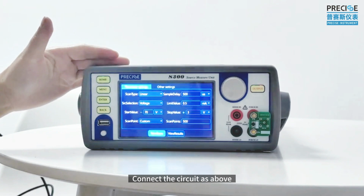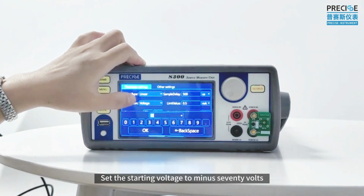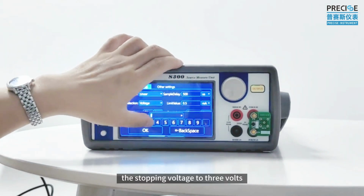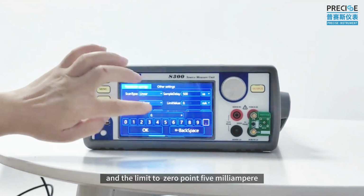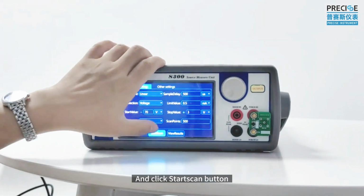Connect the circuit as above. Set the starting voltage to -70 volts, the stopping voltage to 3 volts, and the limit to 0.5 milliamps. And click the Start Scan button.